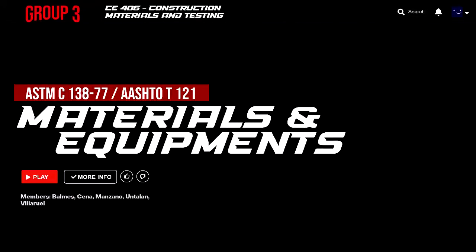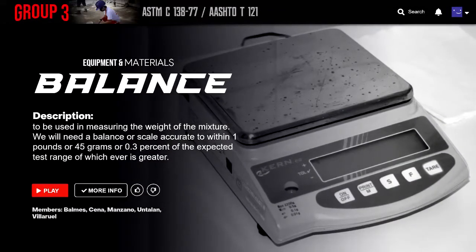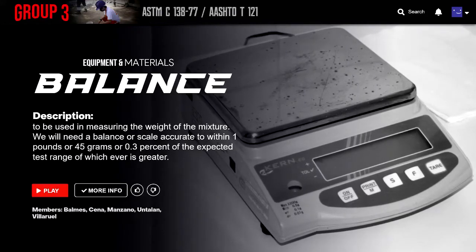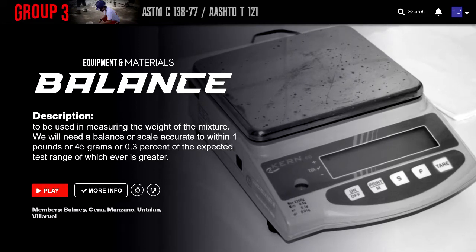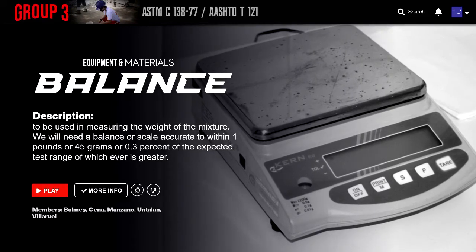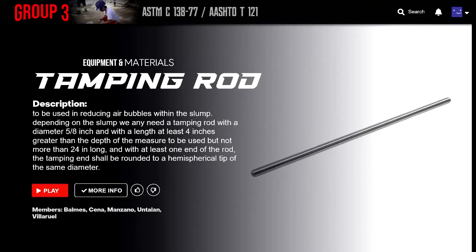And as for equipment and materials, first is the balance, to be used in measuring the weight of the mixture. We will need a balance or scale accurate to within 1 pound, or 45 grams, or 0.3% of the expected test range, whichever is greater. Next, the tamping rod. The tamping rod is to be used in reducing air bubbles within the slump.